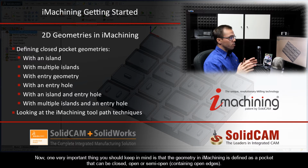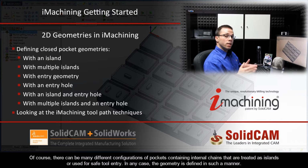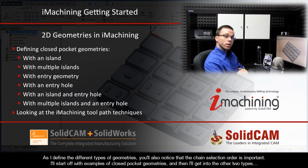Now, one very important thing you should keep in mind is that the geometry in iMachining is defined as a pocket that can be closed, open, or semi-open, meaning containing open edges. Of course, there can be many different configurations of pockets containing internal chains that are treated as islands or used for safe tool entry. In any case, the geometry is defined in such a manner. Now, as I define the different types of geometries, you'll also notice that the chain selection order is important. Just keep that in mind. So I'll start off with examples of closed pocket geometries, and then I'll get into the other two types.